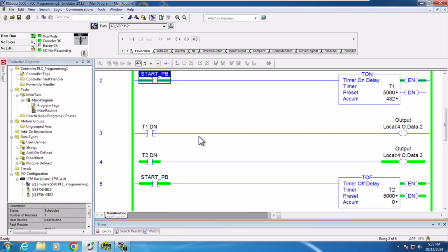As we do this, pay close attention to how each timer reacts. The T-on timer will begin counting every time we toggle the Start button on, while the T-off timer will only activate once the input is turned off. This back and forth will help us understand their distinct behaviors and how they play critical roles in our control logic.